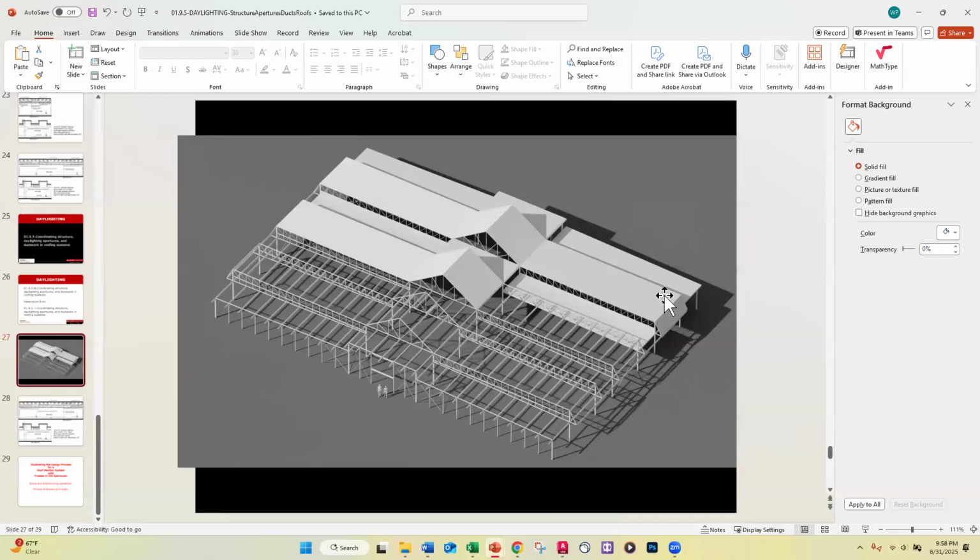But that light would get diffused around, and on a bright, sunny winter day, it would make the space a lot more cheerful. The north light is there to avoid the extreme fluctuations with the coming and going of clouds. The north-facing glass is very uniform and tends to smooth out somewhat the light that's being introduced from the south apertures.